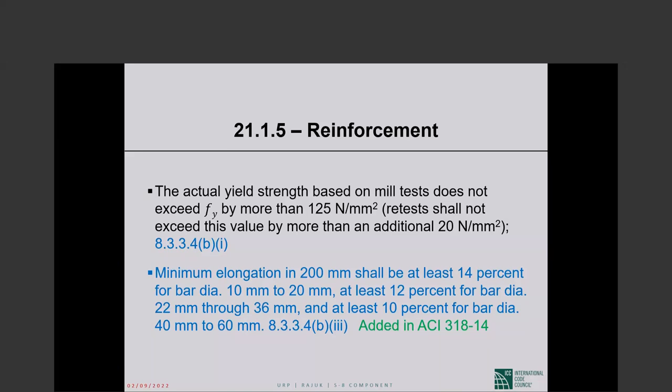Shear and moment, remember, the two are related. So the higher shear force will cause shear failure preceding flexural failure, because we will not be correspondingly increasing the shear strength of the member. And shear failure is brittle, comes without warning. We absolutely do not want it. Okay. So that is supplemental requirement number 1. It is in 318-08. It is in BNBC 2020.